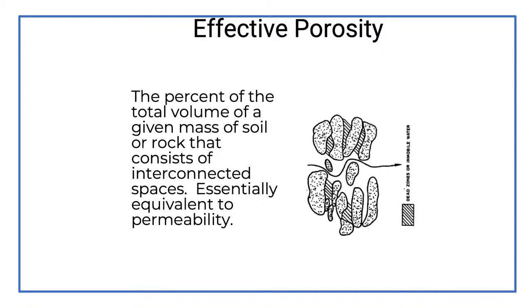Water will have a natural adherence to the sand grains, so effective porosity is always going to be less than your total porosity, because you're never going to get all the water out of the aquifer. It will not happen. Physics comes into play here. These are physical properties of water. It's going to adhere to the sand grains, and it just can't flow out of there.